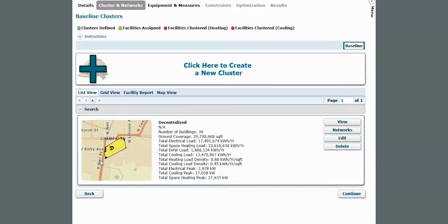If you have a large area like this, which is going to end up resulting in a low energy density, we'll compare this energy density here to the density of the buildings that are on a central network, then it's much more expensive and less cost effective to have a centralized network. I think that may be obvious already, but if you're going to put in a central network with a central plant, then having closely developed buildings and infrastructure in a small area with a high energy density is the most cost-effective way to do it. You minimize the length of those piping runs, which is really the most expensive part or most variable part of putting in that type of system.